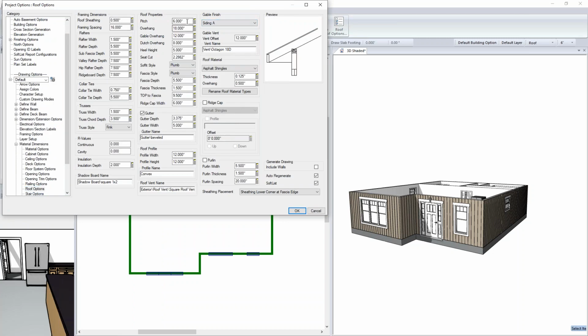Okay, so as I change this, it's going to impact this drawing. Okay, so I change the overall roof pitch to an 8/12 roof pitch. I could change the overhang to something a little shallower at say 16 inches or 12 inches, and I can change the heel height on this to let's say 4.5 inches, so we create a bird's mouth cut there.